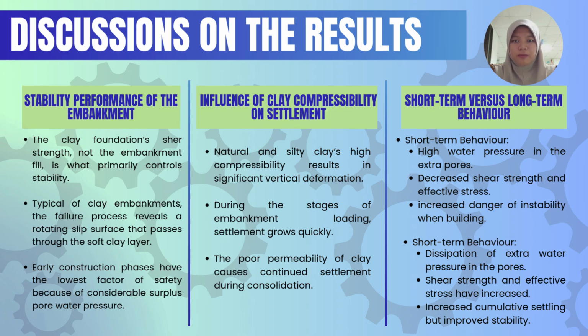This is caused by the high compressibility and low permeability of the clay layers, which result in both immediate and long-term consolidation settlement. Overall, the short-term behavior is dominated by reduced effective stress and lower stability during construction, while the long-term behavior shows improved stability but increased cumulative settlement. Therefore, staged construction with sufficient consolidation time is essential to ensure both safety and long-term performance of the embankment.